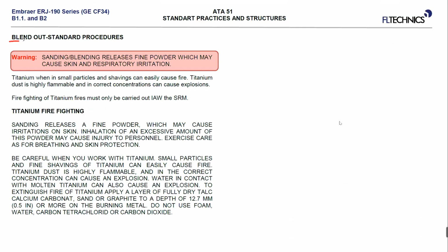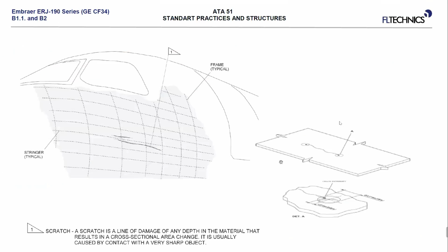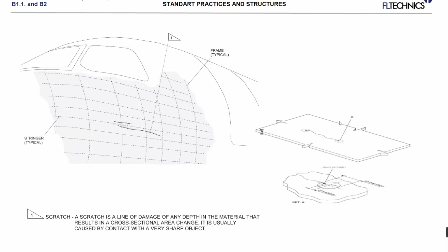Are you familiar with what blend out is? Blending is when, for example, in this case, we have the scratch, and you know very well that all these scratches first damage the layer of the paint, then the layer of primer or some protection layers, and then if the scratch is deep enough, it will also damage the structure.